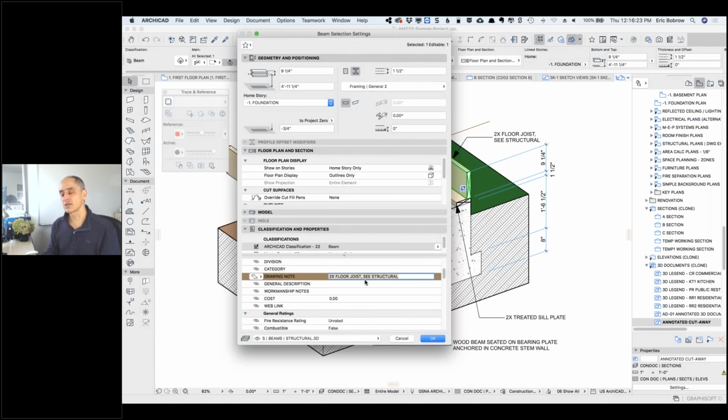The idea here, which I learned from Tim Ball, the architect in the UK who's been pushing the limits of ArchiCAD in terms of modeling as well as data derivation, is that if you have some fields where you put the data into the elements, you can then label them anywhere and everywhere and have them in the schedules with all of that information.